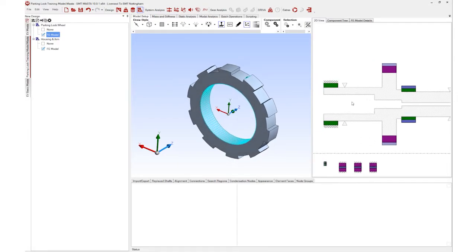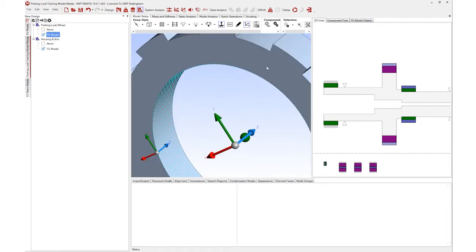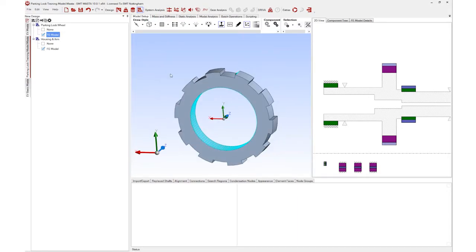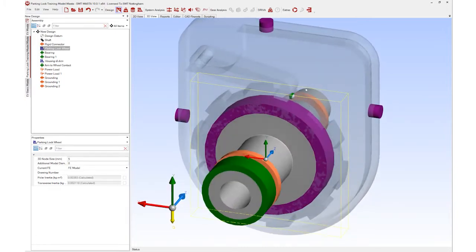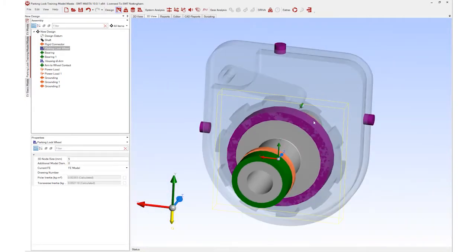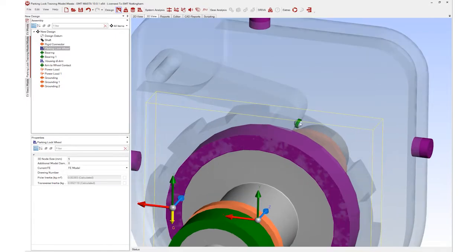So when we try and put a torque through our input load now, it is going to try and put that torque through the housing there, through that park lock ring, and then it's going to transfer that load through this contacting node here into the arm. This is done, as I say, in quite a unique way.